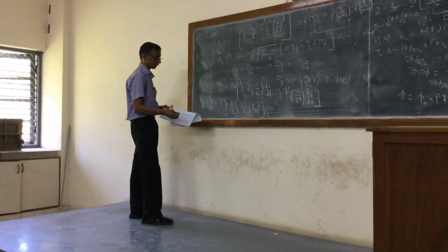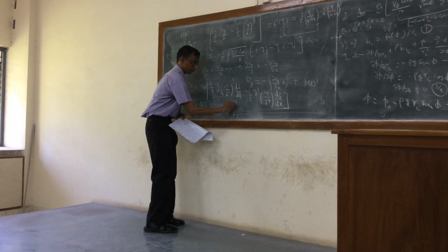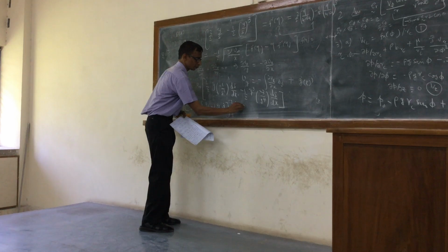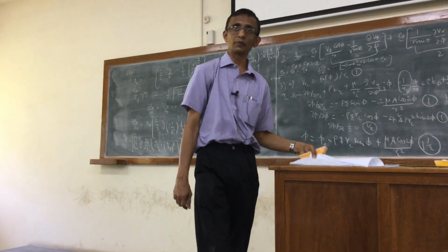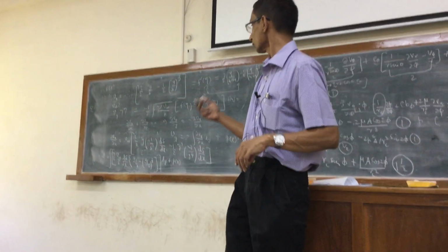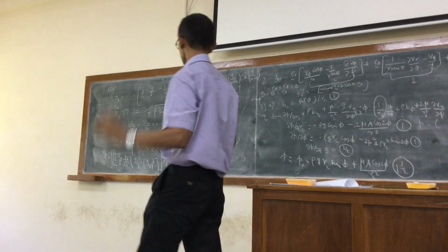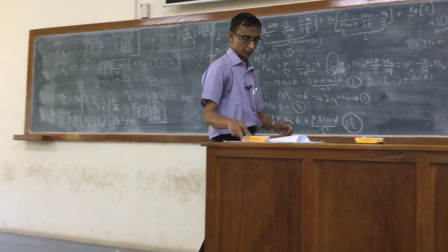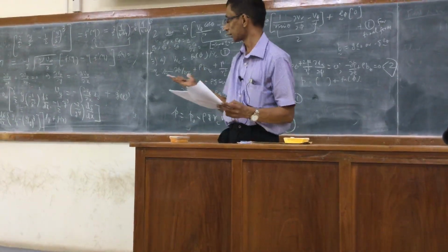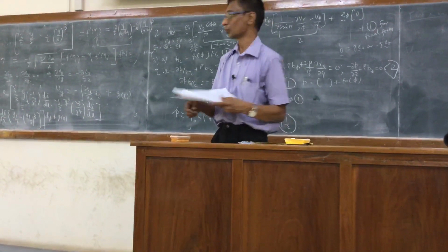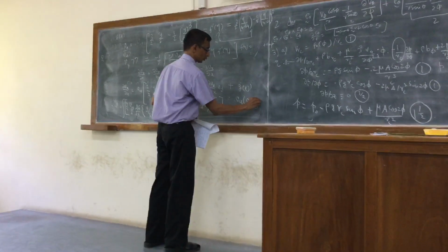And so now I have to integrate this. Vy would be this integral with respect to y plus some function of x, because it is only a partial derivative and Vy is a function of both x and y. So it is easy to do the integration with respect to y. I'll probably give the answers to some of these problems on Thursday, but you can easily show that function of x is 0 by using the boundary condition that Vy at y equal to 0 is 0.